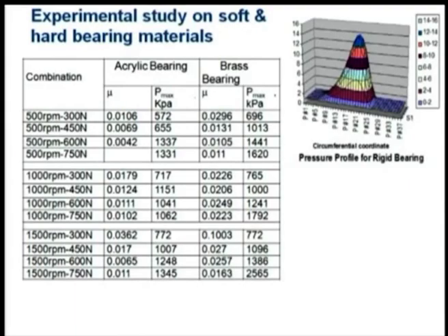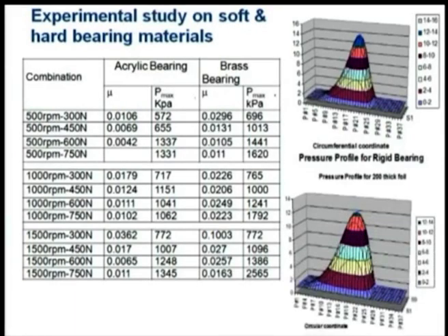If the pressure is sufficient to deform the bearing or the bearing asperities, then the governing lubrication mechanism is the elastohydrodynamic lubrication mechanism, not only the hydrodynamic lubrication mechanism. This is what I am trying to conclude in the present lecture with two graphs. We are showing here a more rigid case, and this is for an elastically deforming surface, even though the materials are the same. Here the material thickness is roughly 3 mm, and here it is slightly lesser, around 200 micron.